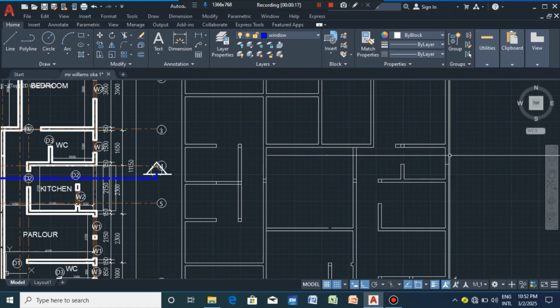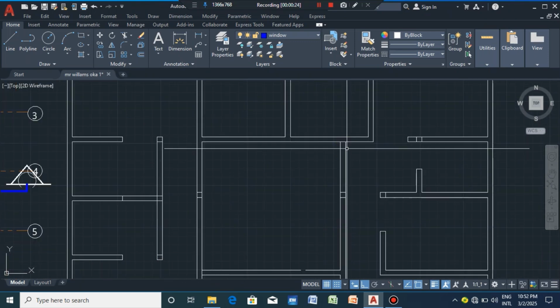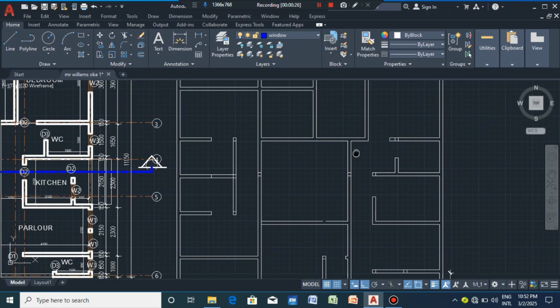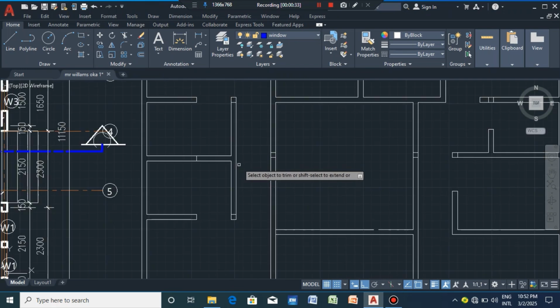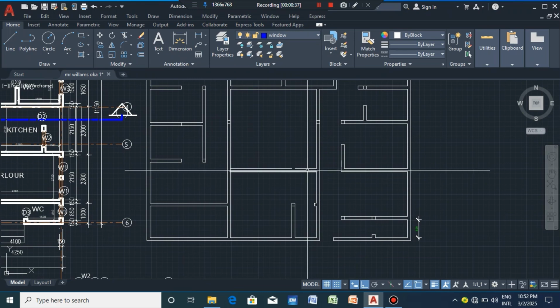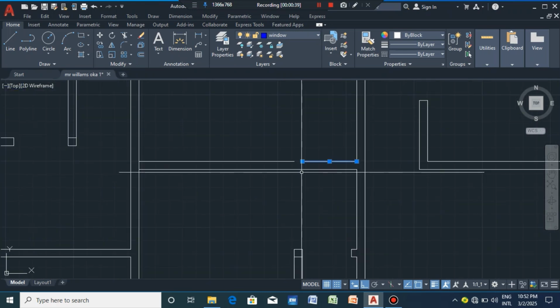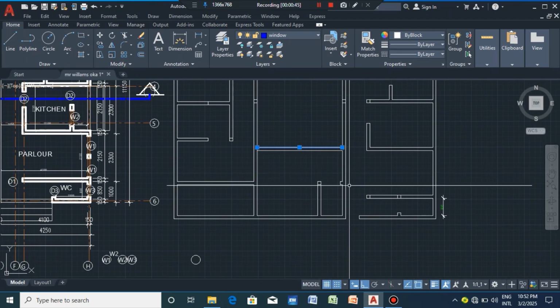So if you check very well, you see that I've made the necessary trimmings. I've made some trimmings to remove some unwanted block walls and all that. Like all these things, they need to be trimmed. All these openings, you need to show that there's an opening here, there's a block passing through this place. Then things like this, you delete them, join them together, to avoid broken lines or double lines.